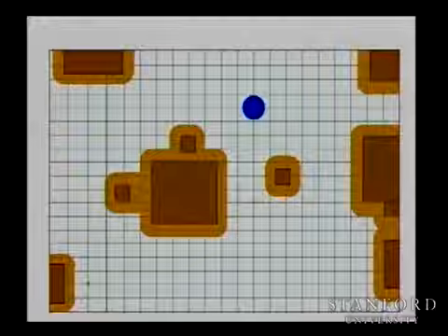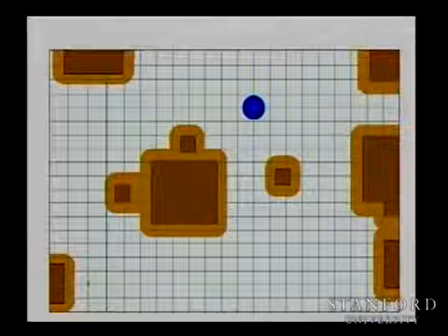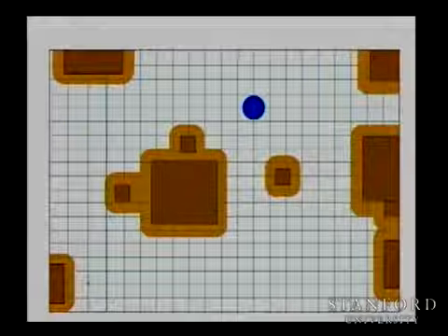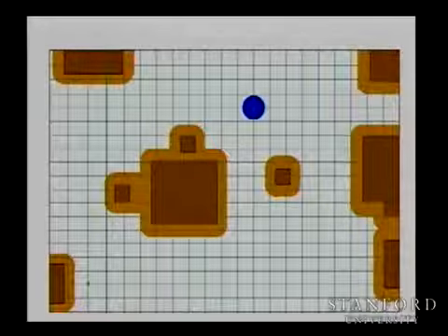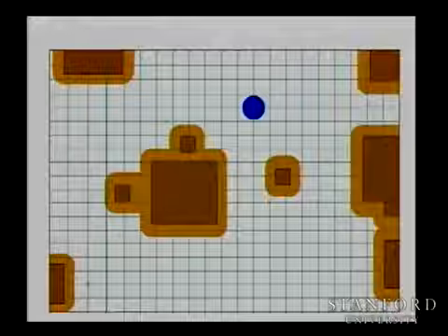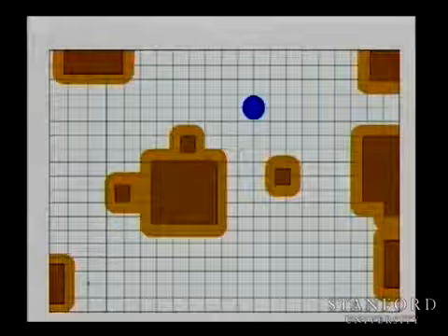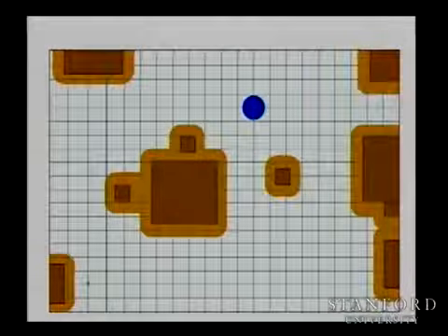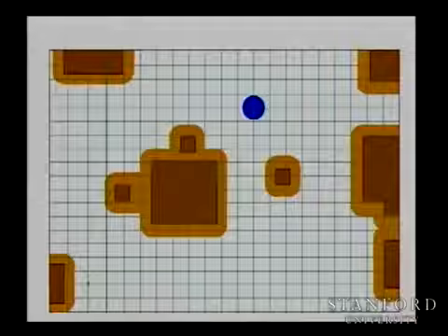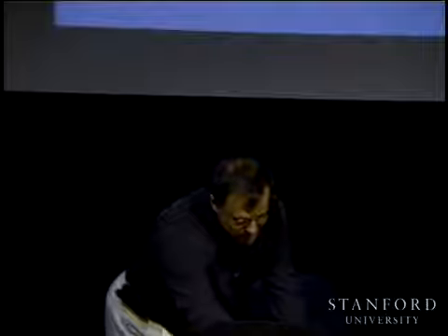If we have a several degrees of freedom robot, or we start adding orientation, then these configuration space obstacles can be not only planar, which is here, but then you get a three-dimensional obstacle because you're thinking about the orientation that you're approaching with. Or you can get many-dimensional obstacles if you have many degrees of freedom. So in its more generic form, that becomes planning for an n-dimensional path in an m-dimensional space. Then you can start talking about, you know, kind of high math there.